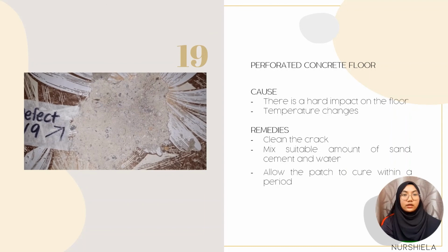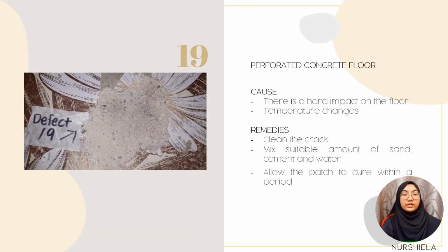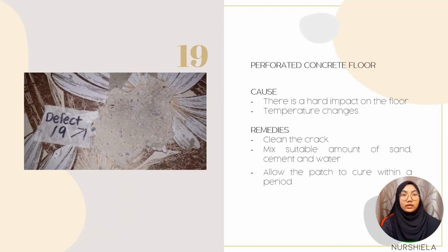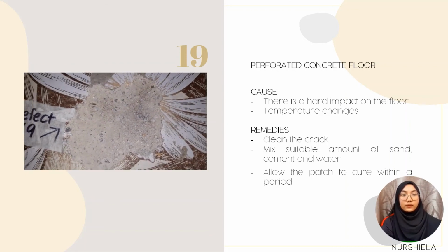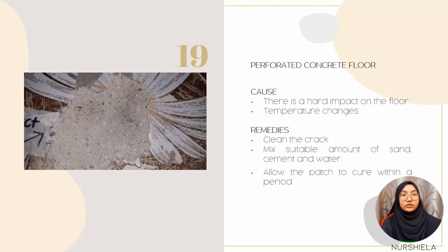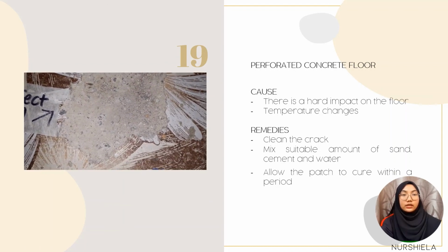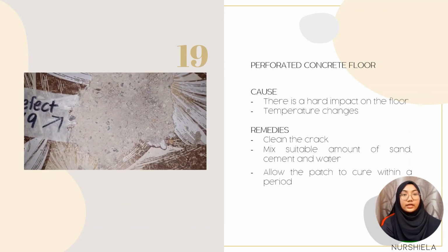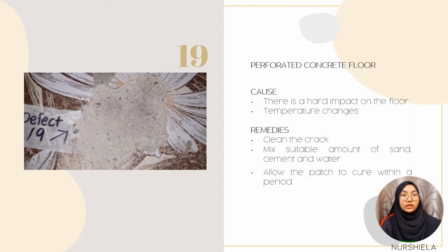Okay, so the fourth defect is perforated concrete floor. There is a hard impact on the floor which causes the concrete to become cracked. So to make the floor better, clean the crack and mix a suitable amount of sand, cement and water. Then fill the crack fully with the mixture. After that, allow the patch to cure for a period.